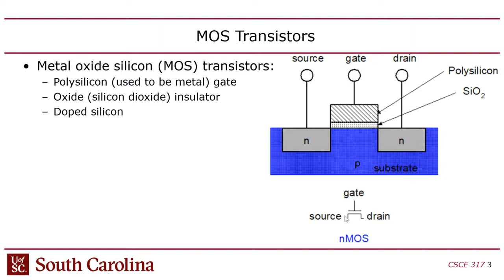The reason is because of latch up. If you have an N-type transistor like the one I'm showing here, the substrate needs to be grounded, and it needs to be hard grounded. You want lots of connections to ground there, because if you keep the voltage of the substrate at ground, it guarantees that you're not going to have any current going from the source into the substrate or vice versa, because the substrate and the diffusion area form a diode. And remember, I said that the current can only go from P to N, and only if the voltage potential of the P side is higher than the N.